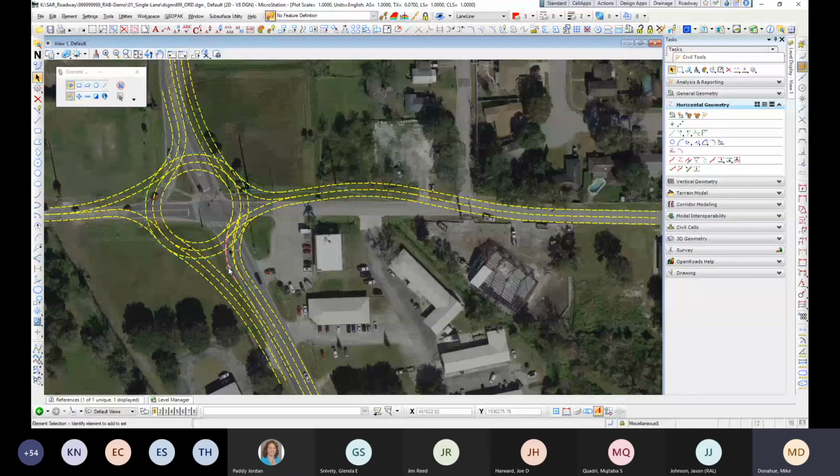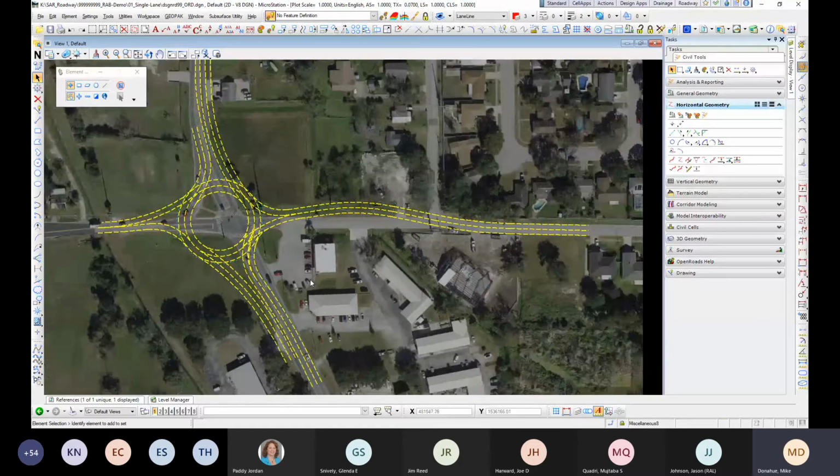I would not run a template on my PGL as a linear template because you have less flexibility with overriding parametric constraints. And I like to use the parametric constraints for cross slope and lane widths and things like that. So I want that flexibility. So I will run it as a corridor. So your template has to be set up to run either on the right side or the left side, depending on the direction of your alignment.